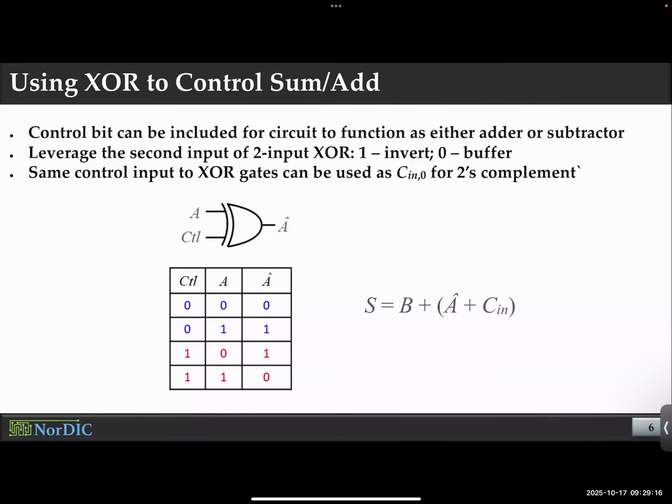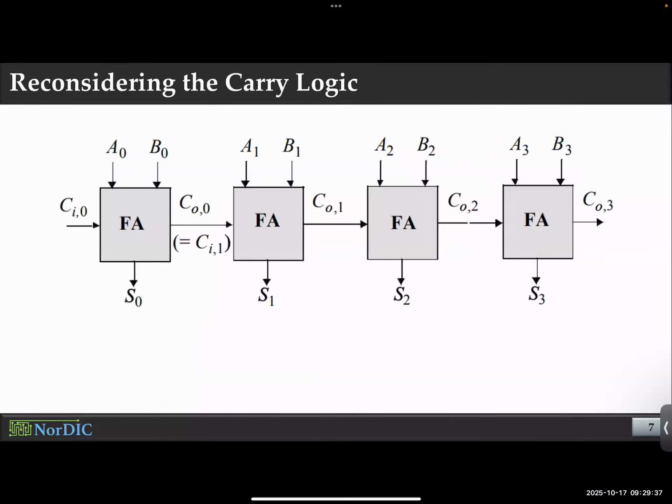So using a simple XOR gate, it is possible to switch between an adder and a subtractor. Here's how. Ready to hear about it, folks? Okay. Imagine you're trying to do b plus a or b minus a. So the only thing that could change is a. It could either be positive or negative. Okay, so let's do that.